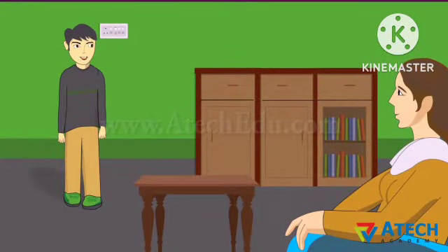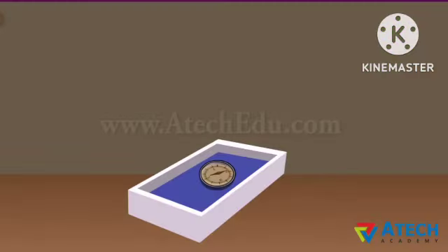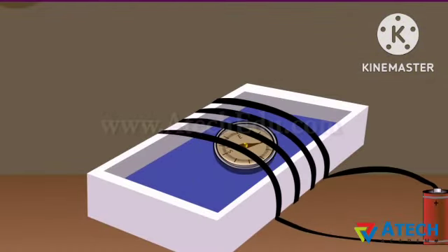Yes, we can make a tester using the magnetic effects of currents. Take a tray of discarded matchbox. Place a small compass needle inside it. Wrap an electric wire a few times around the tray. If you connect the ends of the wire to a battery, you find that the compass needle shows deflection. Thus, our tester with 2 free ends of the wire is ready.